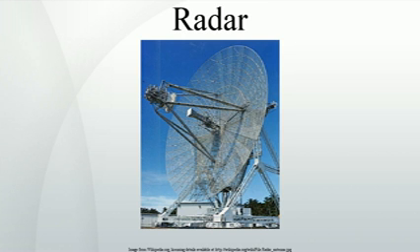Doppler effect. Frequency shift is caused by motion that changes the number of wavelengths between the reflector and the radar. That can degrade or enhance radar performance depending upon how that affects the detection process.